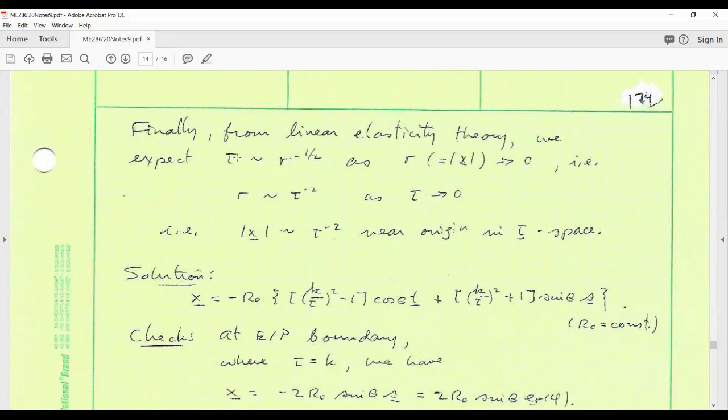Nevertheless, we would expect, for a small plastic zone, the elastic solution is perfectly meaningful in the remainder of the material. So from linear elasticity, we would expect the stress to scale like 1 over square root of radius with some constant, with some angular dependence in front, trigonometric dependence on phi, and some constants also, right? But the radial dependence goes like 1 over square root of radius.